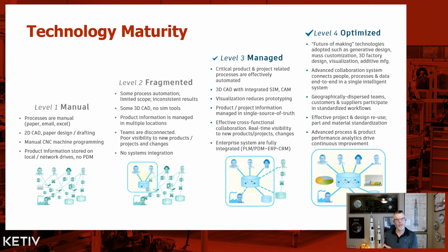So why focus on the 2D drawings? Focus on the 3D models. Do your design reviews. Make sure you have a high level of detail and the models are accurate. And if you do it correctly and you understand the best methodologies of producing your 2D documentation, once again, high level of confidence that the outputs from your 3D models are going to be spot on.